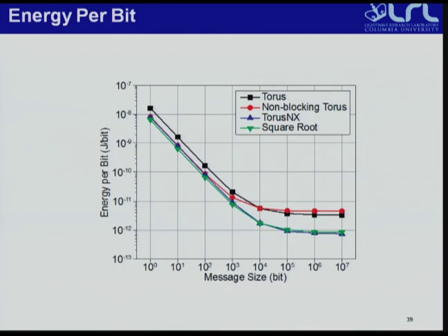If we take a look at the energy per bit that we see between these four topologies, we see that our designs that we optimize for insertion loss are actually a little better, mainly because they have fewer routers and switches, fewer electronic resources, and so they burn a lot less static power, mostly.